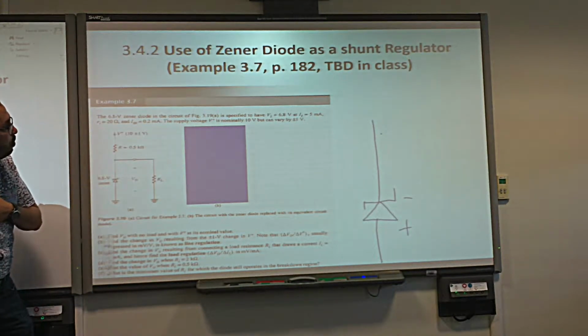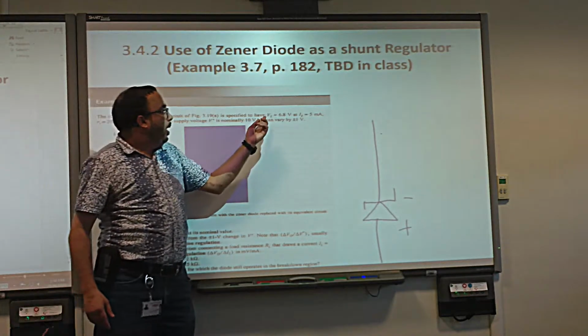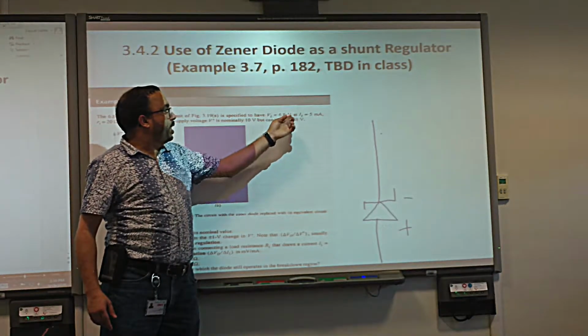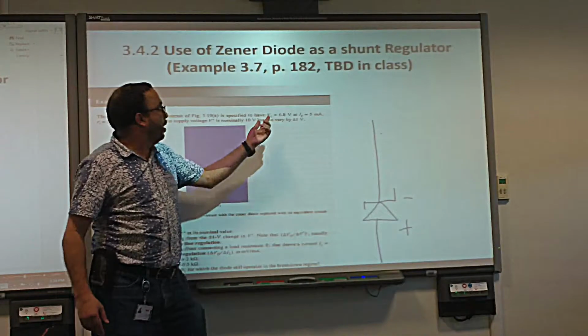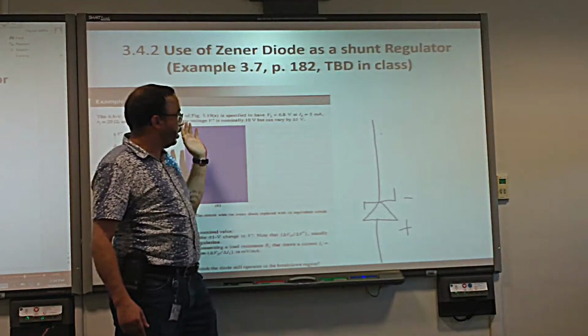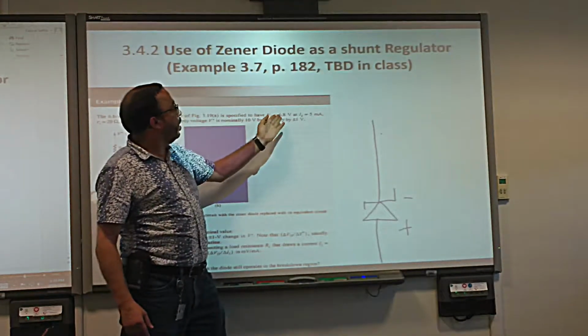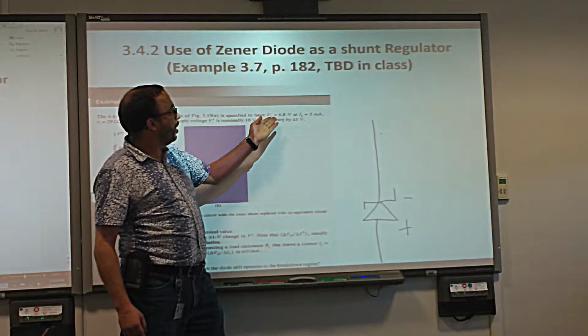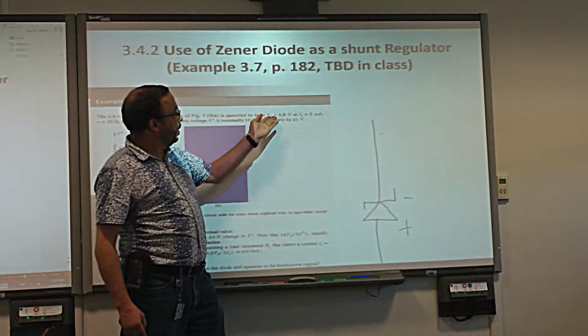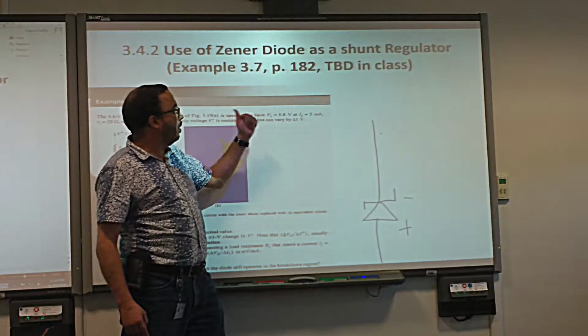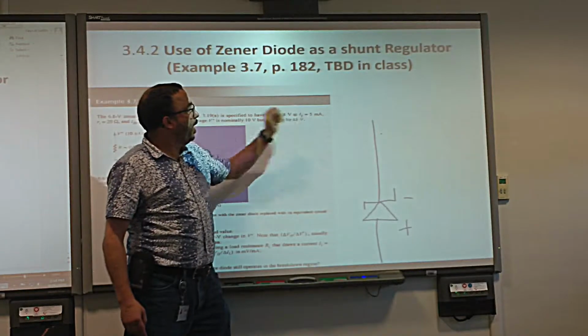What's 6.8, sir? What does it mean? It means it was measured at 6.8 volts, and the manufacturer's data sheet shows us that he measured the voltage VZ of 6.8 in the reverse and gives us a current of 5 milliamps.